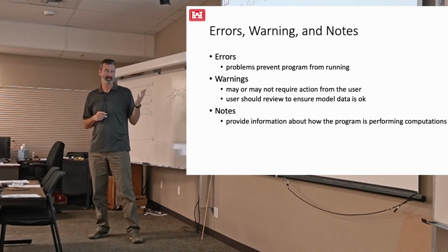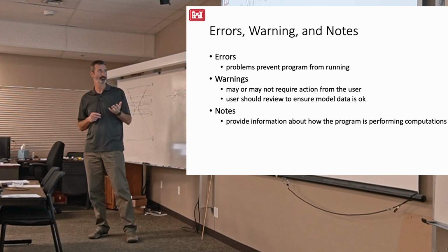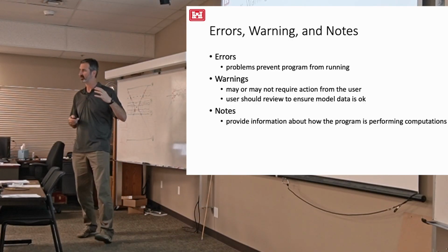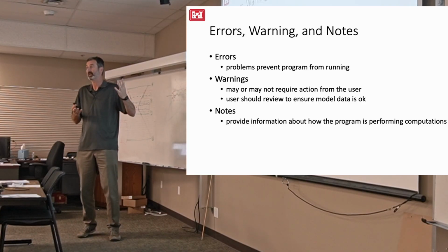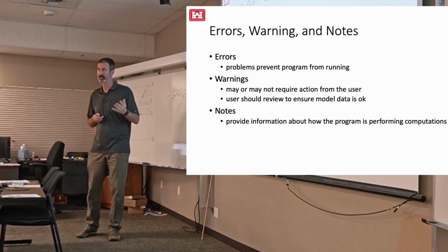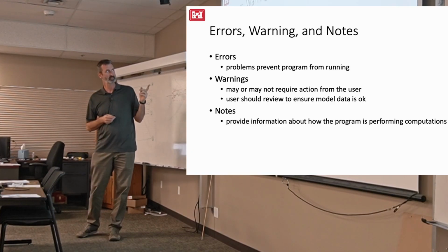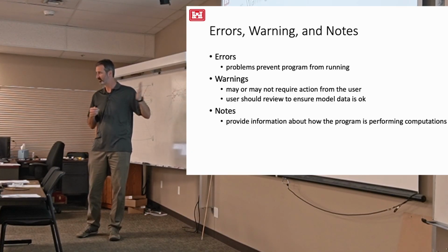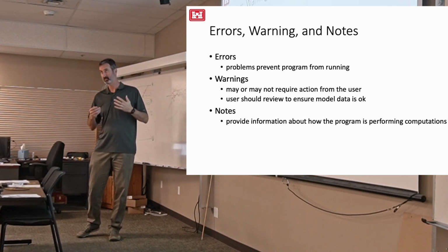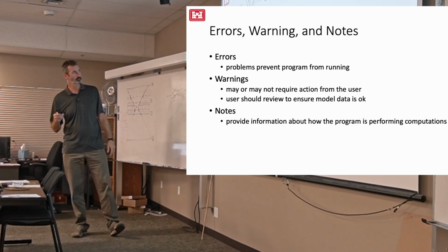Okay, so errors, not too many of those, and they really are what will keep the program from running. And the steady flow engine, I think I had some slides on there where I had it crash, and then years later I tried to make it crash again, and I couldn't find a way to do that. In comparison to unsteady flow, you just make the time step really big and it'll crash right away. But the steady flow engine, even if you have terrible cross sections and they're spaced really far apart, it might give you terrible answers, but it does usually run. Which we'll call a good thing.